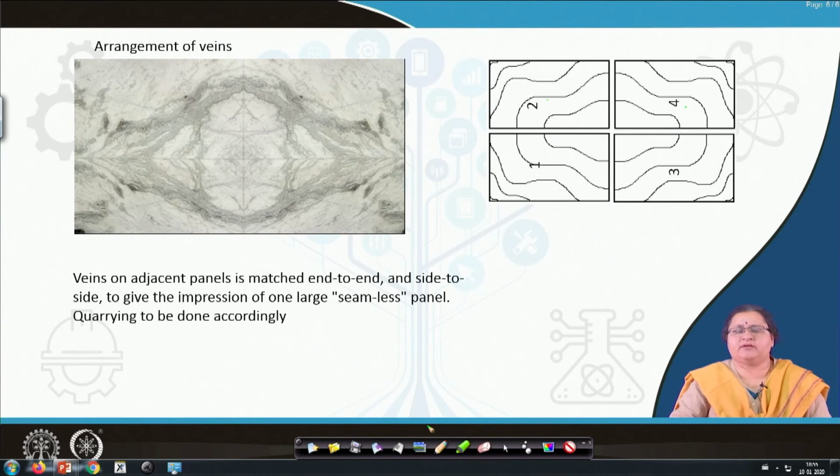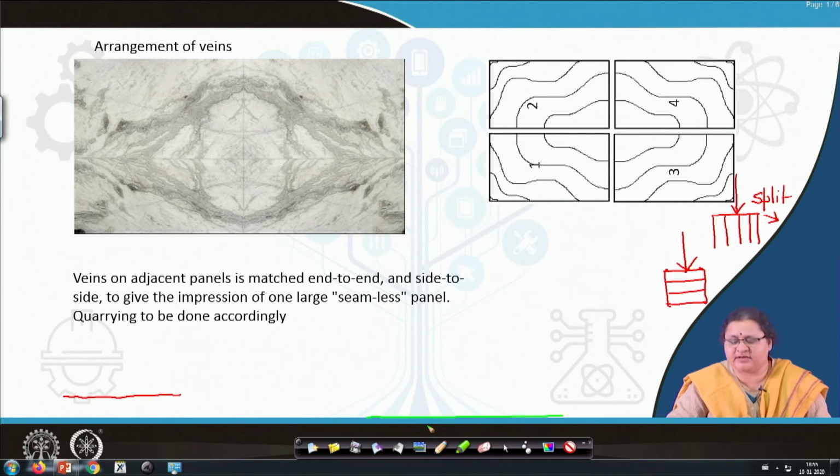You can always recommend Kota stone in kitchen because Kota stone does not take stain. You can recommend Kota stone for laboratories, which is the other place where you always happen to spill some acid or alkali in a chemical laboratory. So you have to remember what is the purpose, where will it be used, what will be the footfall, whether it should be withstanding the weather condition continuously or it is an indoor area. Based on that you can recommend your selection, recommend your stone.